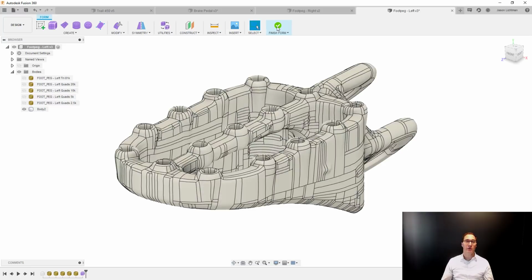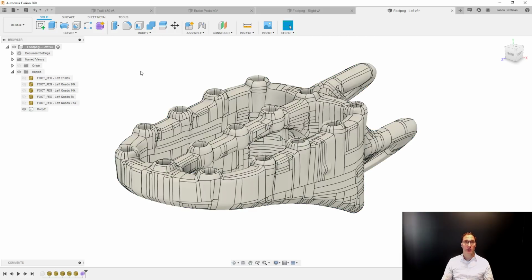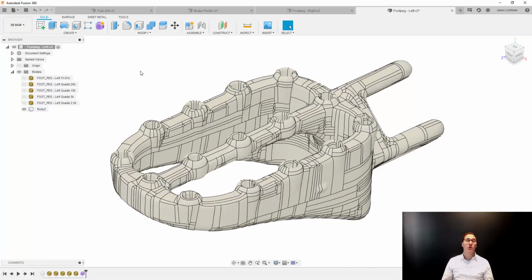And you're going to see here that the number of faces that I have here is a lot less than a one-to-one conversion of the quads. I started with 20,000 quads, and I don't have nearly as many faces as a B-rep. I actually have as few faces as our software calculated you needed to be able to make this into a solid. This looks a little bit ugly, and in some respects it is,